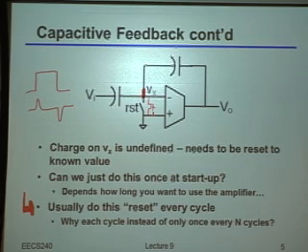Whereas if, for example, you just did this once every 10 cycles or so, now you'd have this repeated, once every 10 cycle, basically spur sitting in your output spectrum, okay, which is typically bad news. Does this make sense to everybody?